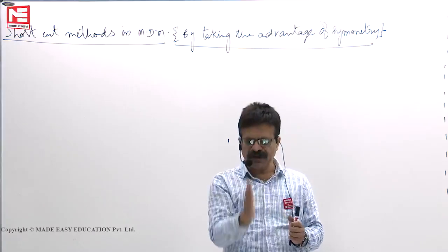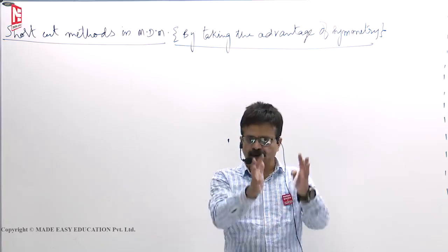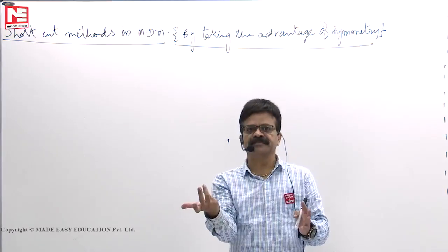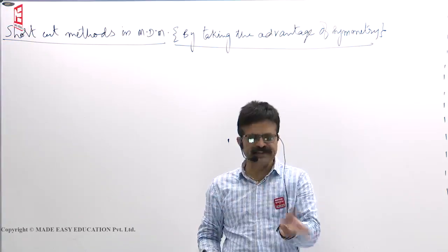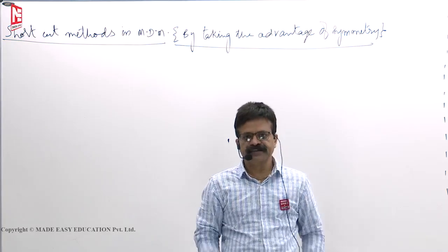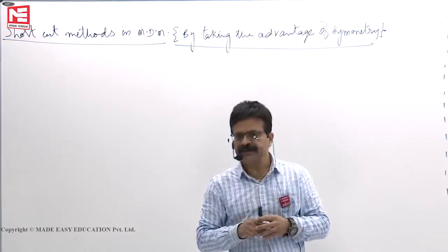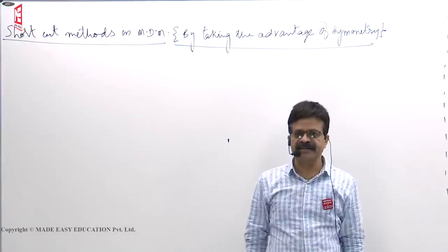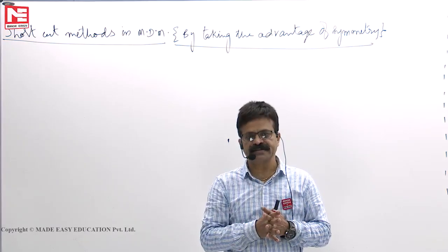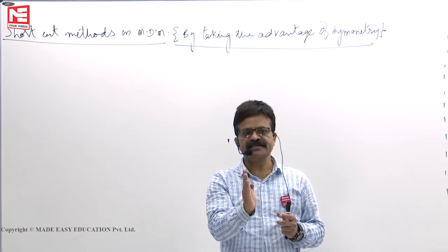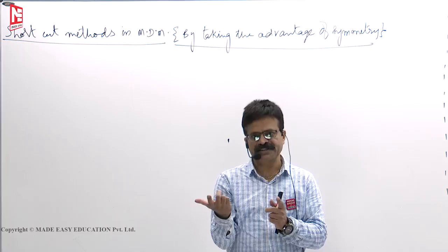In such cases, if you analyze only half the frame, half the beam or half of the truss, whatever member forces you get, just with opposite sign or with the same sign, you can show on the other side. Same member forces must exist. Just when you fold it, they must match. That is what symmetry means. Here also, if you have a continuous beam or frame which is symmetrical about an axis, then with respect to that axis, forces on the left side and on the right side also must be symmetrical. Mirror reflection must be there.